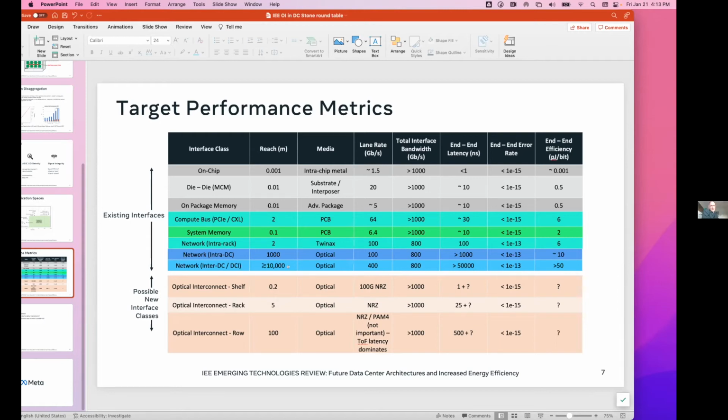By the way, once you start talking about SOAs, that's where NRZ starts having additional advantages, because with PAM4, the noise onto the lower levels from something like an SOA starts dominating your BER, and now you either have to compress the waveform or you take disproportionate SNR hits, starting to offset the amplification gain. So once you're talking about SOA in particular, the simpler the modulation format, the better off you are. QPSK does pretty well too. Right, even better.